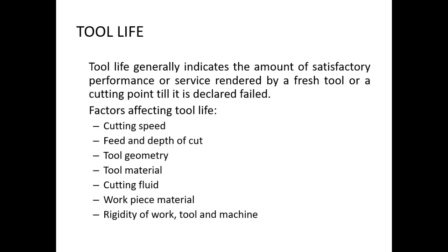Feed and depth of cut: if I increase the depth of cut and feed rate, obviously the tool life will decrease. Tool geometry, we must select a very good geometry. And tool material: if I want to cut a very hard material, I must take a cutting tool that is much harder than the workpiece, isn't it? If not, the cutting tool itself will fail. That is tool material.